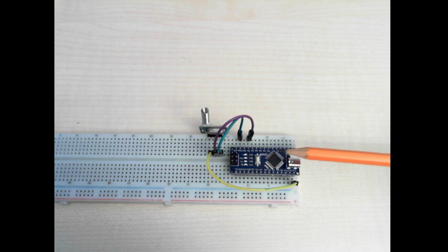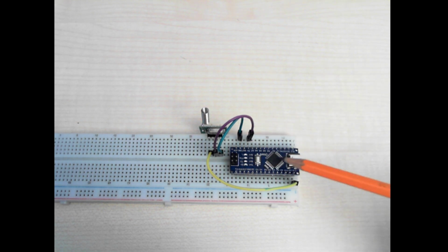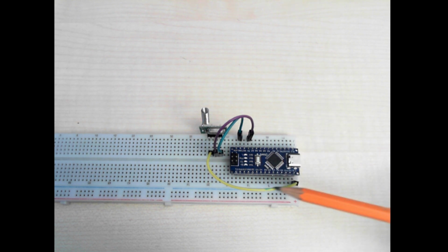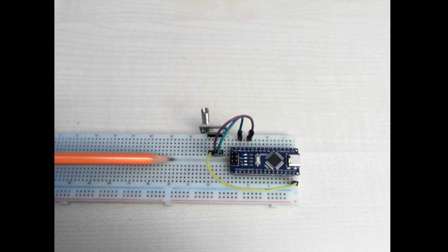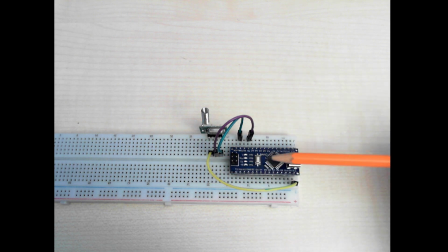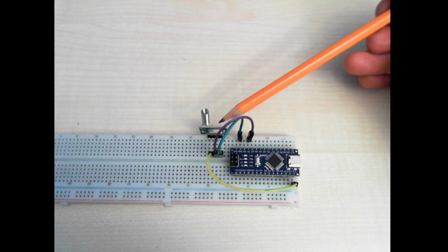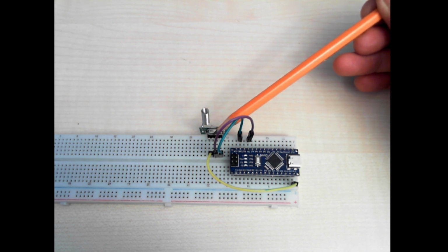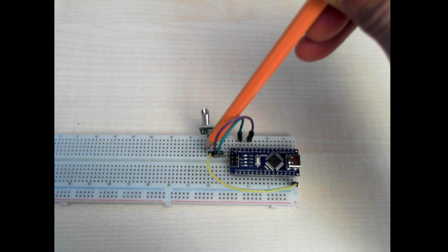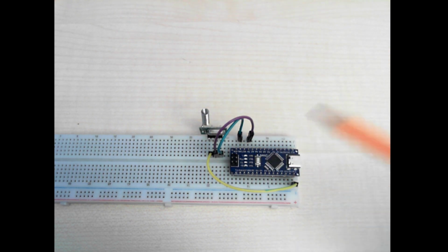I have here an Arduino Nano board, which is actually a microcontroller, an Atmel microcontroller, the chip that you see here. I've placed this on a breadboard. Remember on a breadboard that the central ridge breaks the connection between these vertical points and these vertical points. So make sure that you put your Arduino Nano across the bridge and you place it like this. Then you can put the transmitter module here on any of these sets of the vertical pins and start wiring them up. I will show you the wiring diagram.